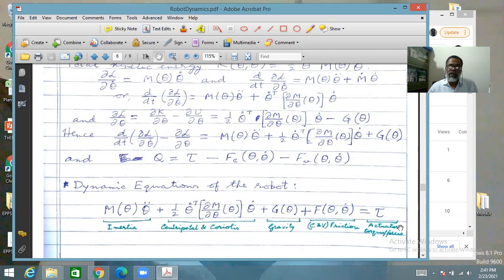So this is the system of equations. Here you have the inertial terms. Here you have the secondary terms. Basically, this is a quadratic expression of all the theta dots. Now in which some of the terms will be theta i dot squared. These are typically the centrifugal components, and some terms will be theta i dot theta j dot. They will be the Coriolis components.